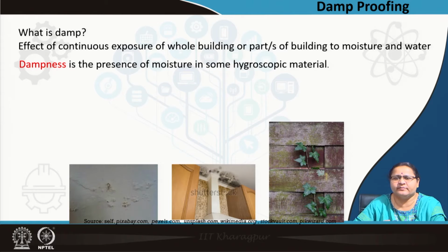We try to make our building as impervious as possible, but as you remember in our very first module, we had talked of brick which actually absorbs up to 20% water. We have wood, another building material which also absorbs water. We are looking into constructions where brick is mostly used, foundations. So, water is bound to enter buildings if we are not protecting it.